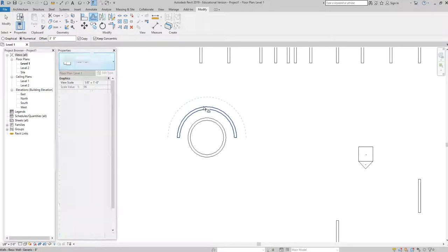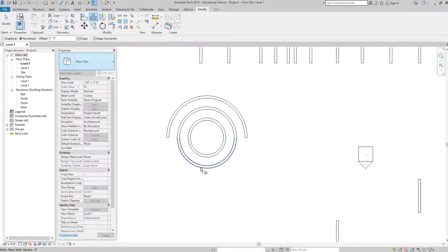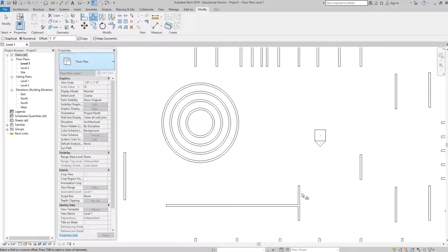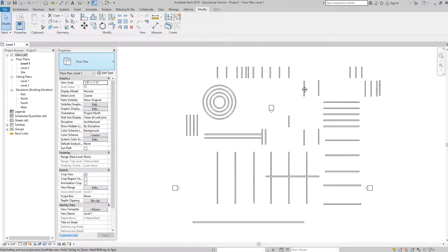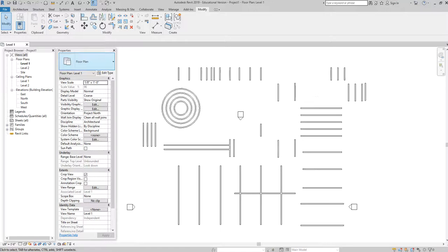Click, click, click, click, click, click. You can just go around and start offsetting walls. Okay. Again, this works with doors and windows and walls and furniture and reference planes and a whole lot of other things. Okay. All right. Lots easier to use than in AutoCAD. Well, offset's not terrible in AutoCAD actually, but I feel like this one's really visual, which I like.